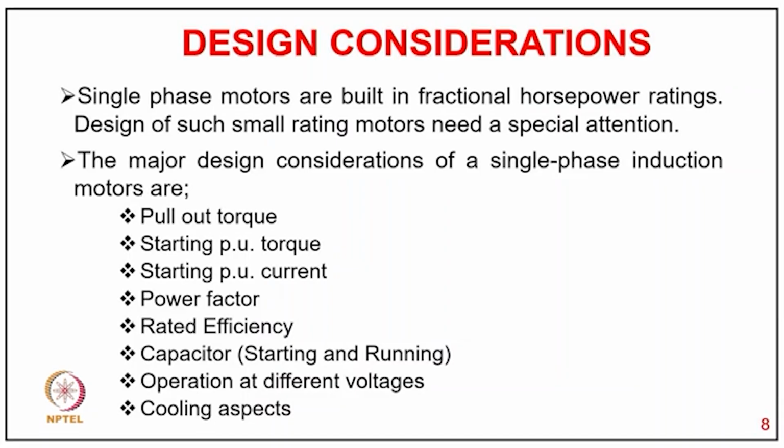Major design considerations of single phase induction motor are typically pull out torque or maximum torque, then starting per unit torque, starting per unit current, then power factor, pull out power factor, then rated efficiency, and then the capacitor value for starting and running, depending on the type, which we discussed last time, and operation at different voltage and cooling aspect.